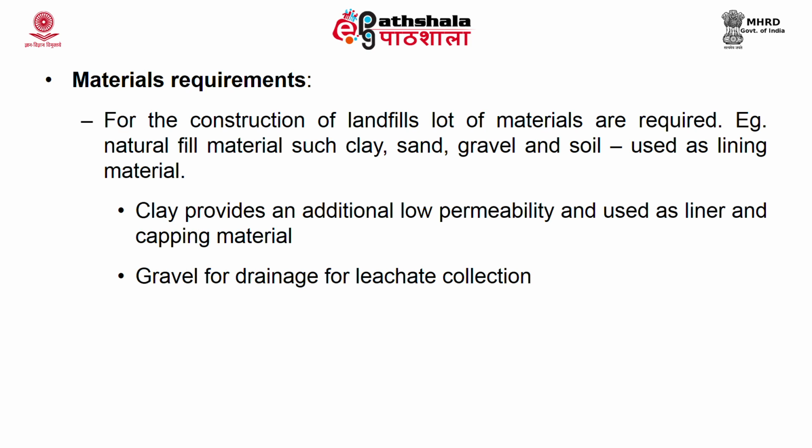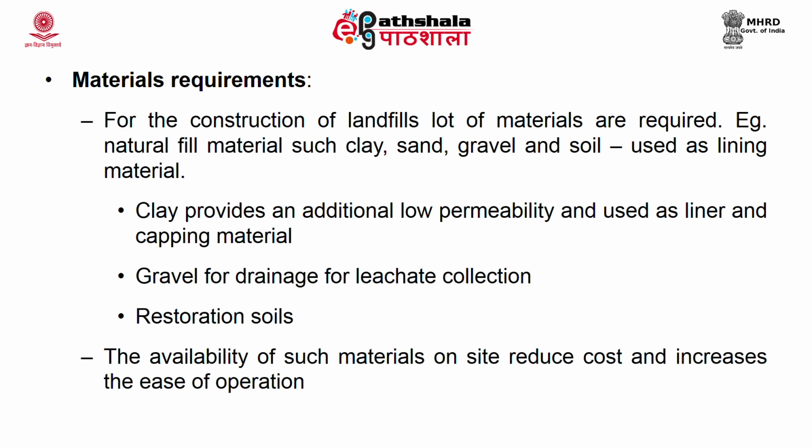Gravel is used for drainage and for leachate collection. Clay is also used as a capping material and for restoration of soil. The availability of such material on site will reduce the cost and increase the ease of operation. On the other side, if these materials are not available, then you have to spend a lot of money for importing or transport, which will increase your cost. So, if the material is available on or near the site, that will reduce your cost.